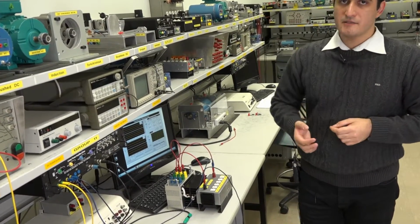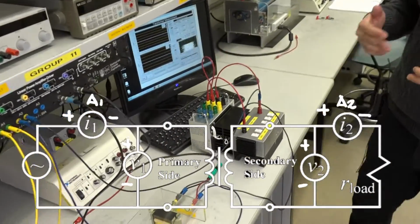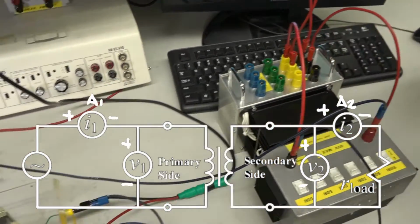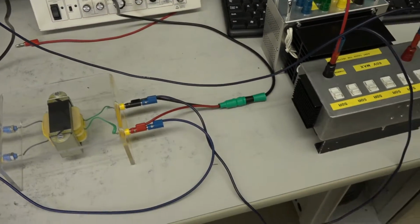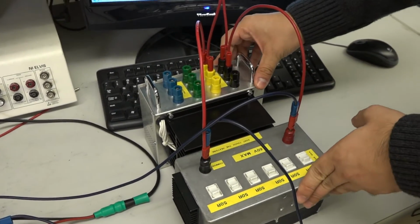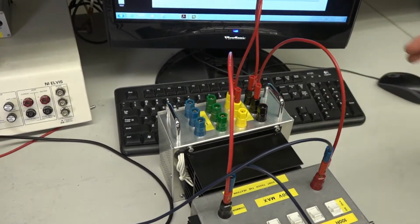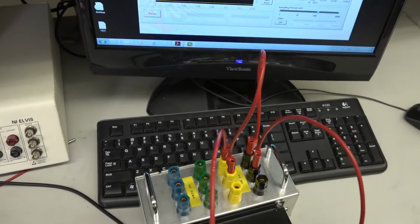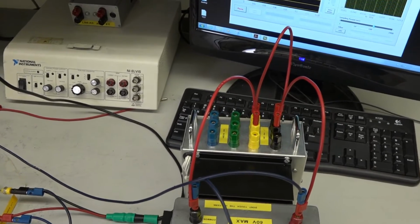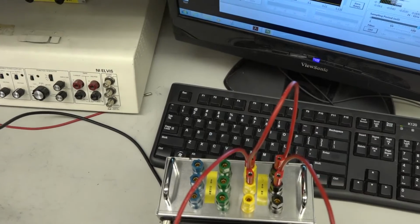So another test that we are going to do on our transformer is the load test. In this test, we will put an electric load on the secondary side. In the lab, you will do this first as a completely resistive load, a resistor; then an RL load, a resistor connected in parallel with an inductor; and then on a third case, an RC load, where you connect a capacitor in parallel to your resistor.